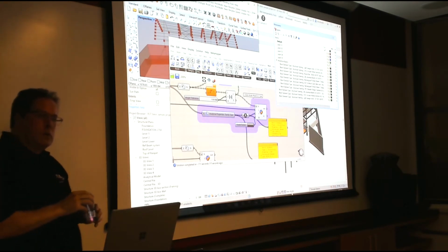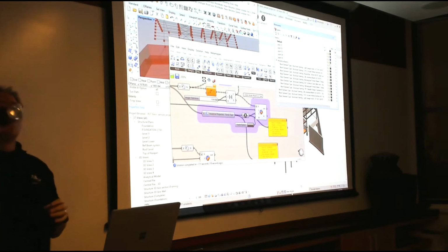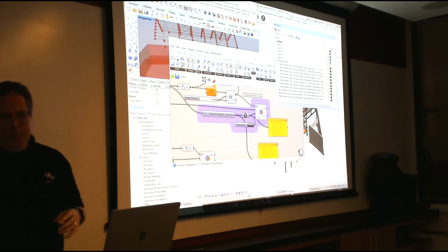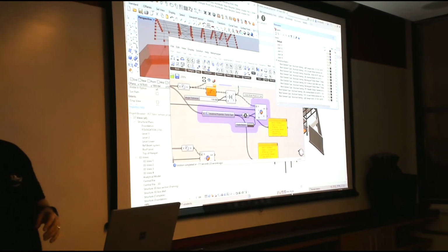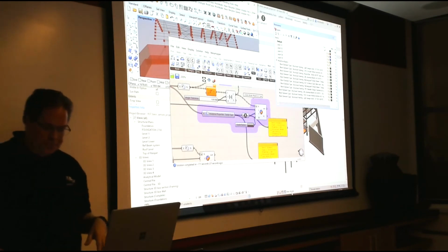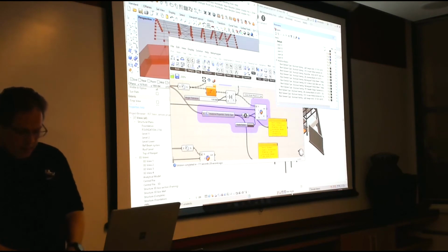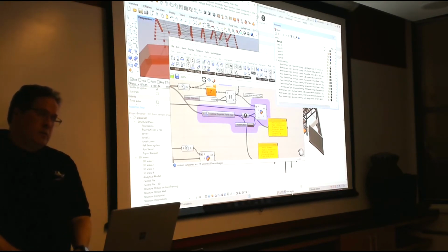So then if you were to have, is there a button to access Revit's like model groups, and then parse through that model group, like core level 41 is composed of stairs, walls, and whatever? If you can get to it through Revit's SDK, you can get to it through Grasshopper. Right, so that would be a custom Python component. If we haven't wrapped groups directly, that's correct.